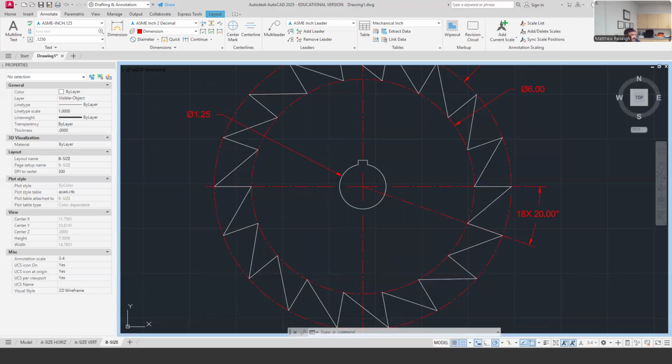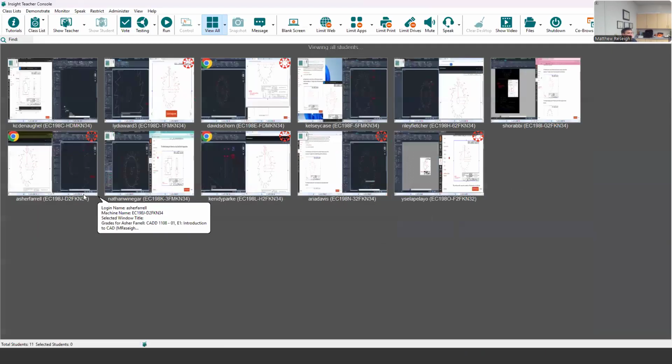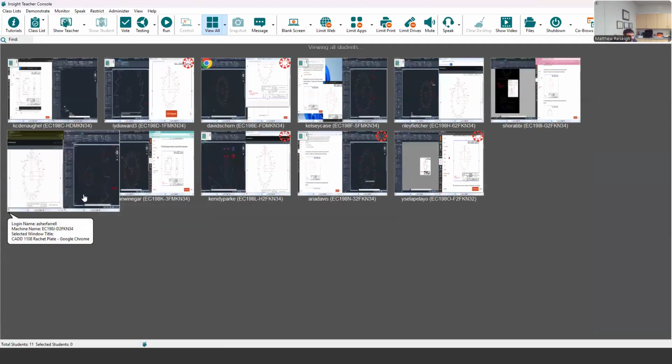We found that you can't just scale something up and have everything scale right. Sorry, I jumped off there so Sky can log in. It was a poor choice that we made, and it cost us a lot of broken parts and wondering why. And the reason why is the shaft diameters were too small for the loads that it was seeing.